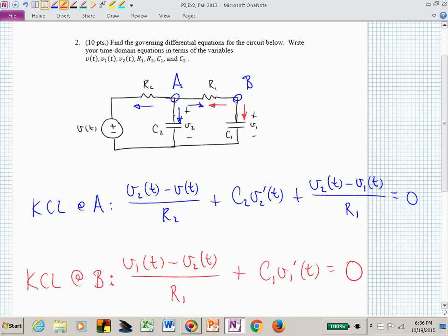Two. What's the order of the circuit, or the order of the equation that this circuit represents? Second order. The first equation you had from A only really gave you a first order. You needed another first-order equation to give you all the governing equations that describe the dynamic behavior of this circuit. So you needed B because you have two independent nodes, and you have two energy storage devices.